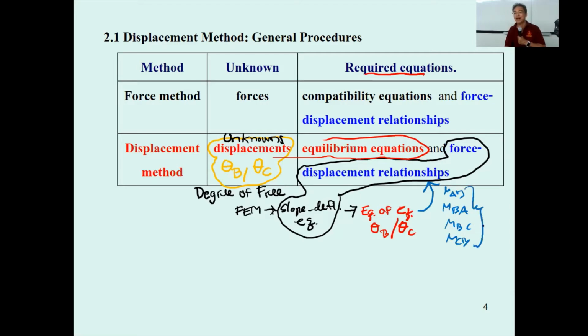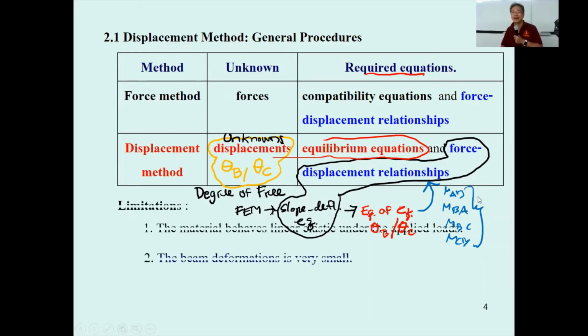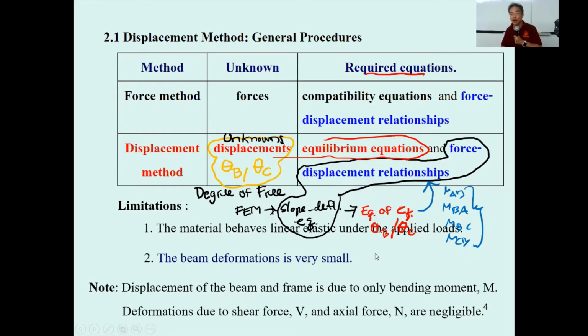Later you use these to draw the shear and moment diagrams. Again, the limitation: the material is linear elastic under applied load with small deformation, and I should mention the deformation only occurs due to bending.